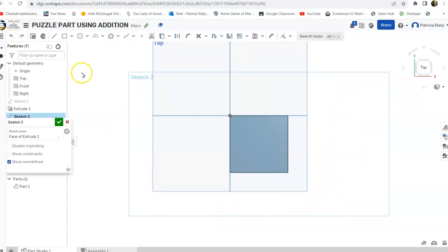Okay, let's make another sketch using my corner rectangle. And let's say I'm going to put this over here. So I grabbed it from the corner. And I'm going to make that, can I make that 0.75 here? Yep. And then let's go ahead and make it also 0.75 there. Boom. Okay, so we have a nice little cube there. Okay, let me think about this for a second. I think I'm going to go ahead and extrude that, so I'm done with that.